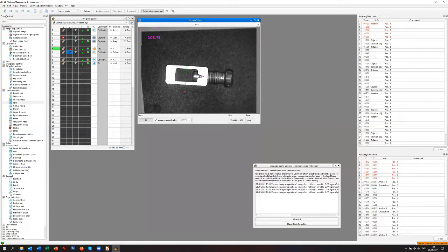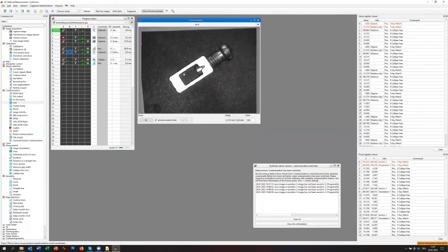And now we see here we have this 106, and if we move it, because the caliper moves with the part in the right direction, we stay also if the part is rotating with the same 100.6 instead of what we saw before, because if you have a fixed caliper, the edges are moving relatively to the measurement, to the distance measured here in the field of view.